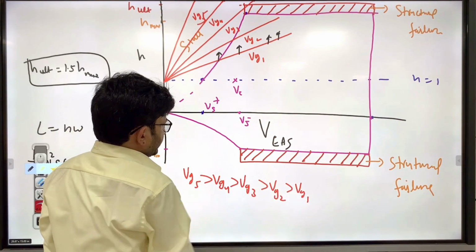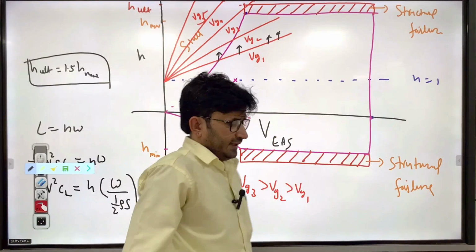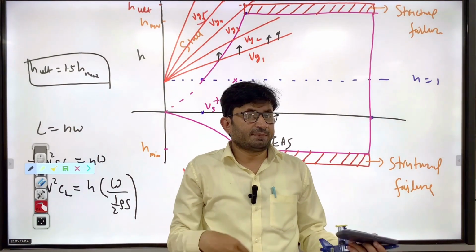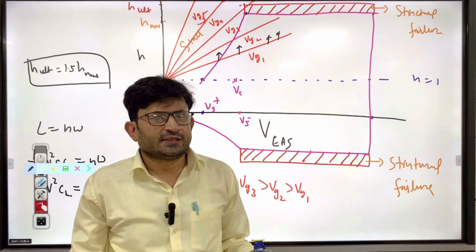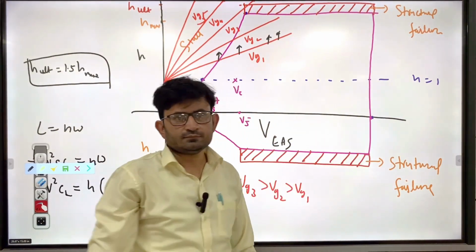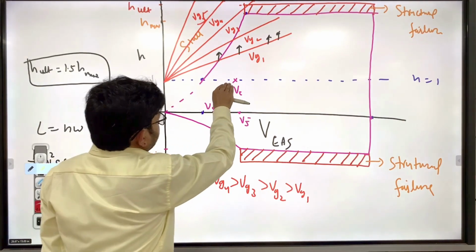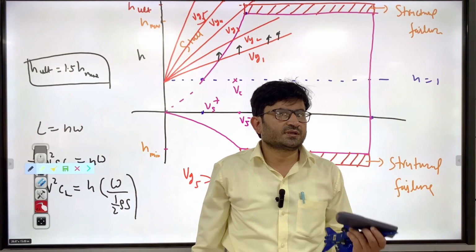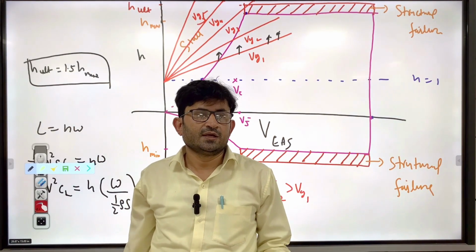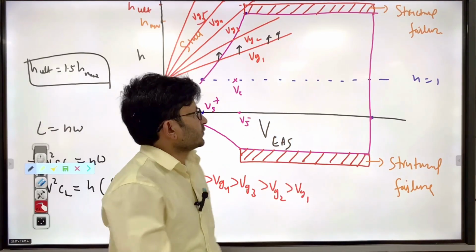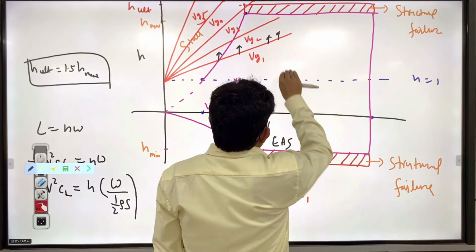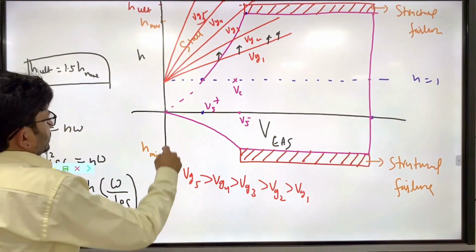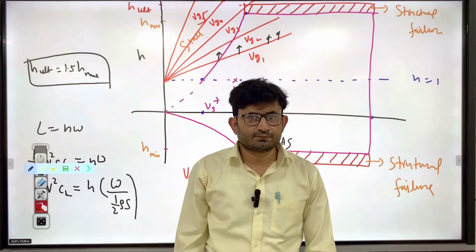so that you can clearly say that this is my structure failure case. Similarly, for the negative load factor case also, if you have any problem choosing this limit, you can simply take multiples of stall speed 2, 3, 4, 5 and draw this line. And if you have any confusion in selecting the design speed, you can select 1.2 times V stall, 1.3 times V stall, 2 times V stall as a design cruise speed. You can see at different trim speeds how the gust is affecting, so that you can have more feel. Right. So this way you can actually draw the VN diagram.